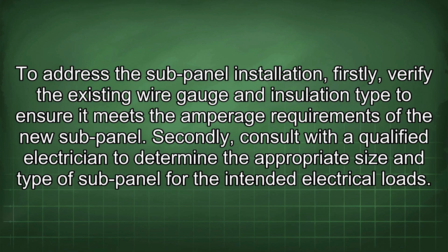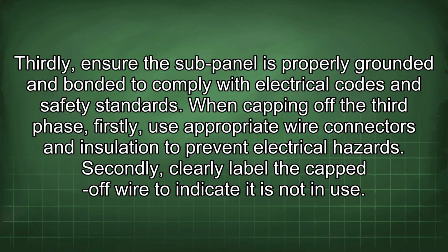To address the sub-panel installation, firstly, verify the existing wire gauge and insulation type to ensure it meets the amperage requirements of the new sub-panel. Secondly, consult with a qualified electrician to determine the appropriate size and type of sub-panel for the intended electrical loads. Thirdly, ensure the sub-panel is properly grounded and bonded to comply with electrical codes and safety standards.